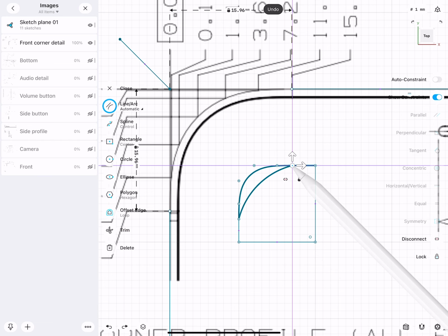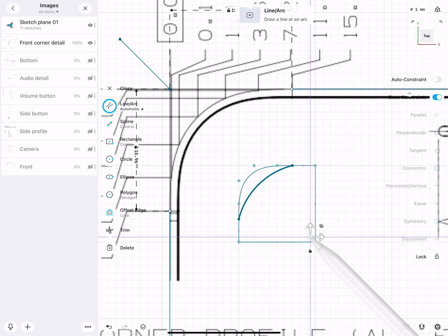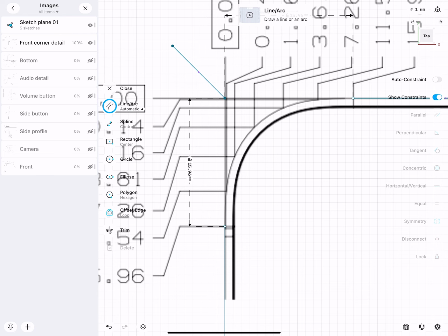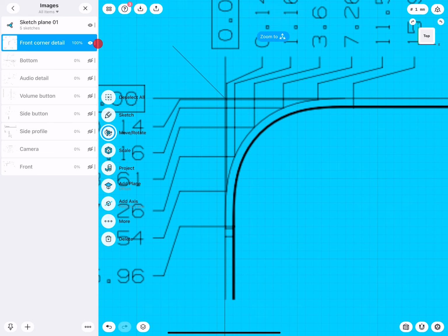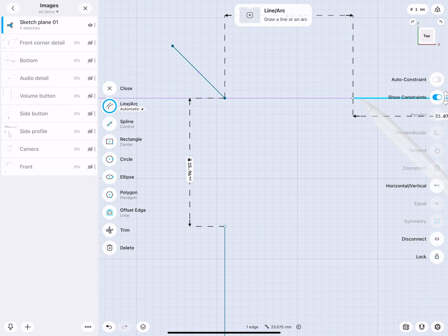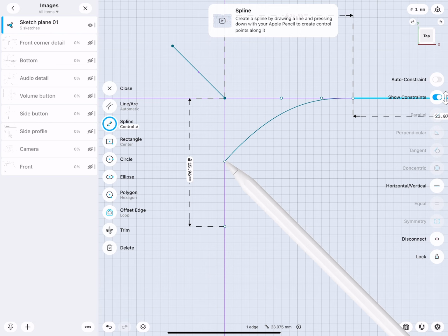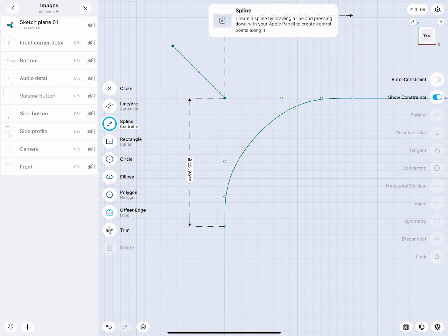Oh, let's actually lock these points. There. There you can see now the difference between G1, the arc, and the custom curve we sketched. Okay. So with this basically covered, what this means is now we can go ahead, and from here we need a control point spline. So one's for tangent, the second is for G2, then another one for G2, another one for tangent, and then we connect it.